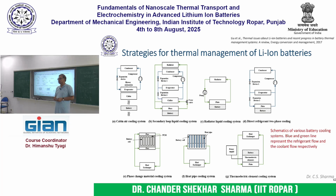Does the working temperature for the heat pipe depend on the working fluid which is used in it, or are heat pipes designed for different temperatures? So the working temperature of the heat pipe will depend upon the working fluid and at what pressure it is charged in the heat pipe. So for example, water, its boiling temperature is 100 degree C, but depending upon the pressure at which water is charged, I can achieve different working temperatures because I am changing the saturation pressure. So then the saturation temperature is also changing at the same time.